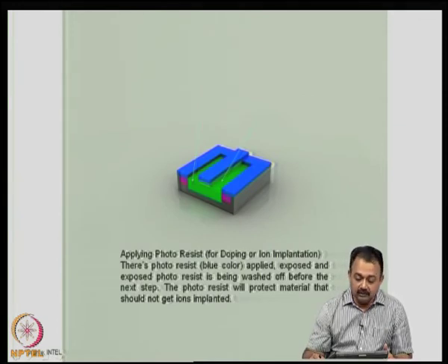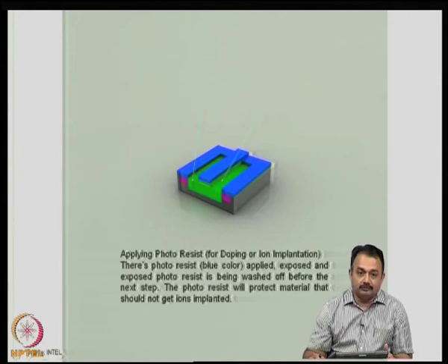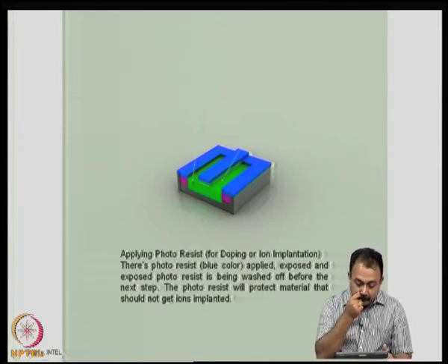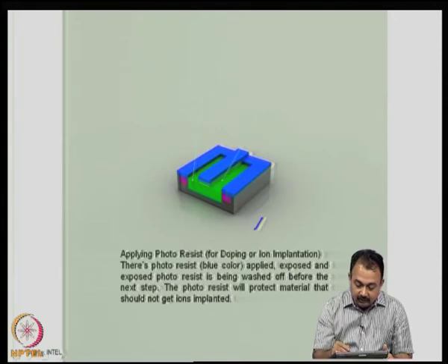These are some of the dopants. They are used to change the property of the semiconductor to improve the electron mobility, and therefore, the next step will be in those areas where the transistors are going to be defined, you are going to do some kind of a doping. So, you have to predetermine what dopant you are going to use.